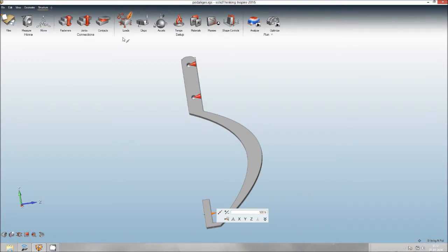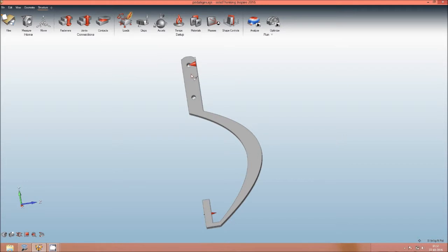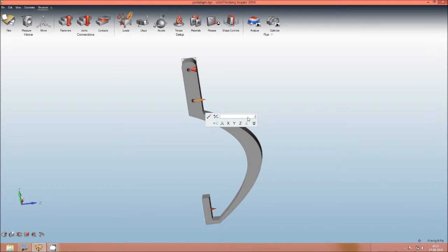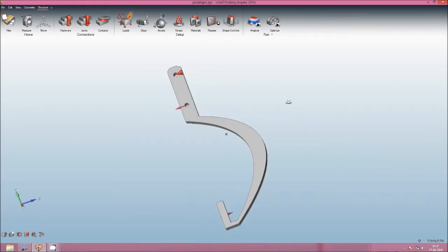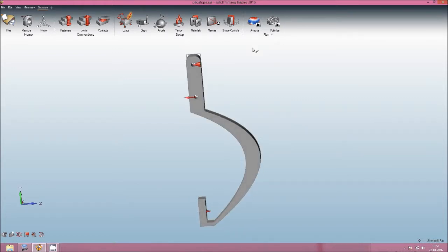Okay, so here the load will not come, so let's remove this part. Instead, the support, not load, support, will come here, and the load will be the one that we got from the mechanism result. I'm applying this arbitrary value. Now we'll analyze the structure.